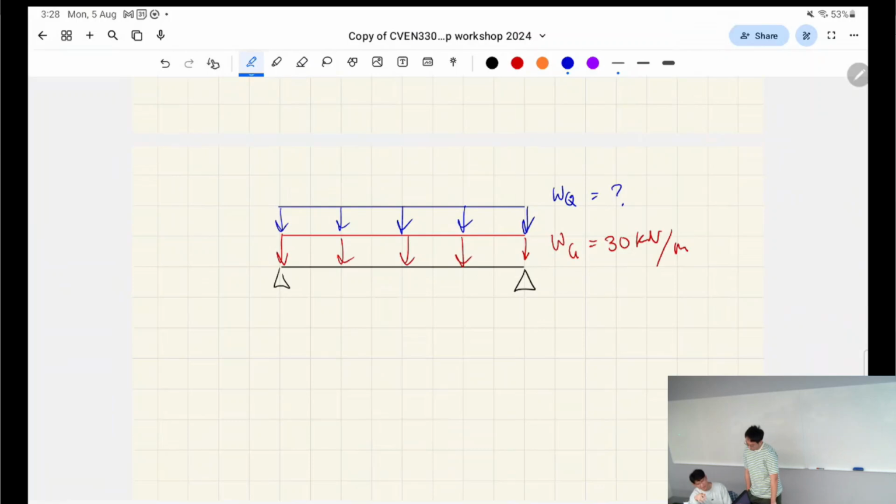What value of live load does it need to be in order to split the threshold? So 1.35G, 1.2G, and 1.5Q. Right. So what value does it cause? It causes this top one to govern for live load.